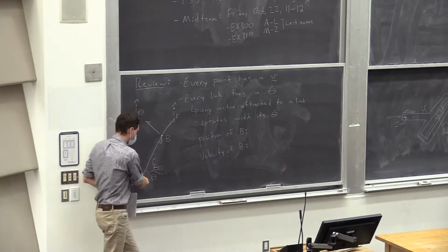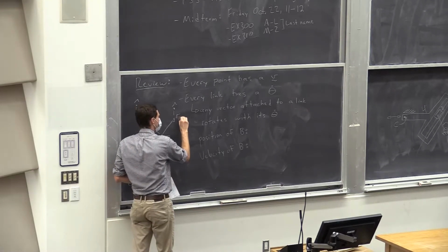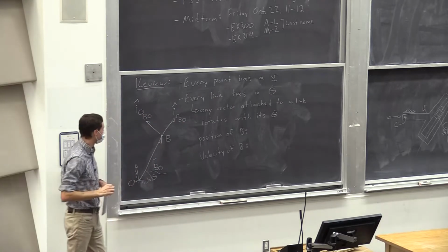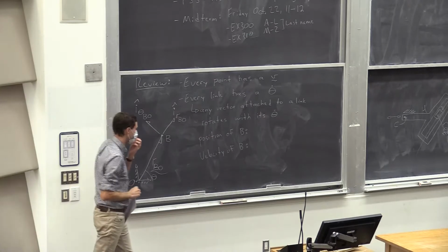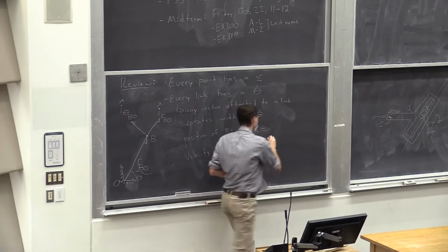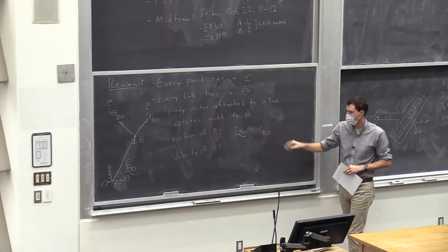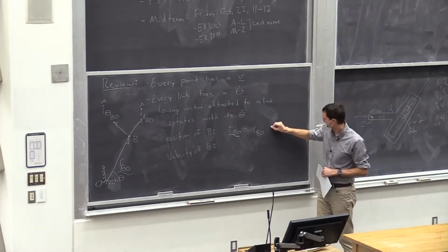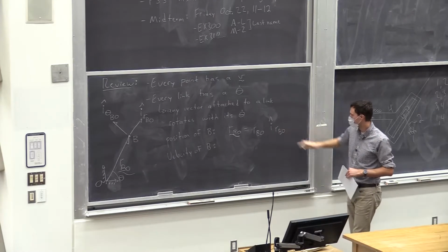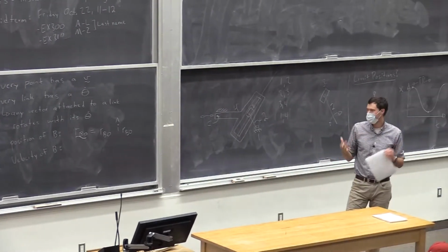And these are specific for this vector only. Every other vector would have its own set of coordinates. So we're going to put the subscript on there anytime that it's not obvious which ones. So that's our radial and transverse coordinates, which allows us to write out that position vector as a magnitude, just r_BO without a vector underneath it. That's just the length of that vector and its direction. So that's how we express position vectors in this radial transverse coordinate style.